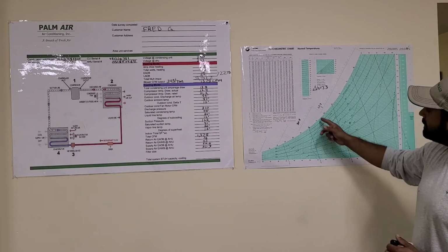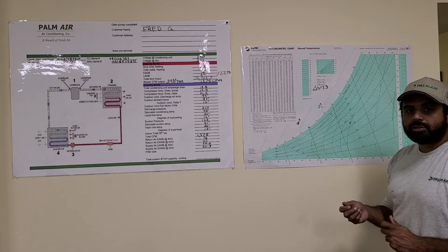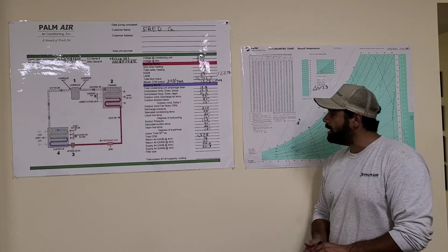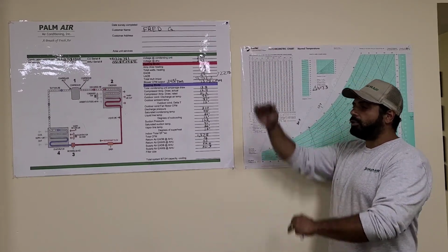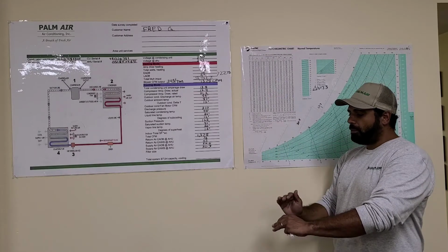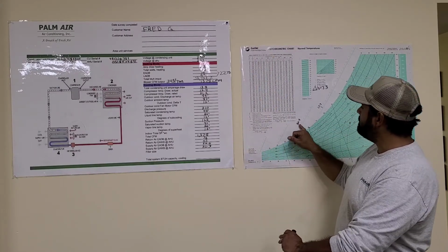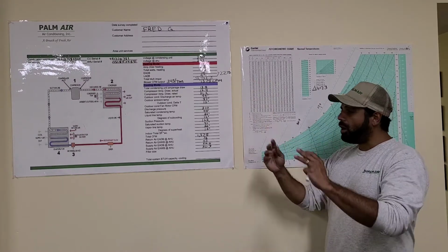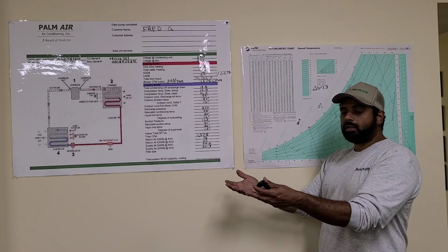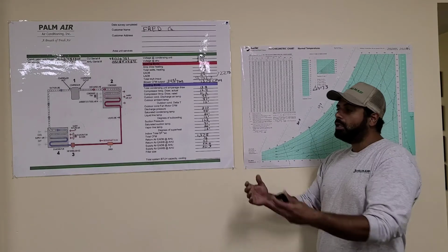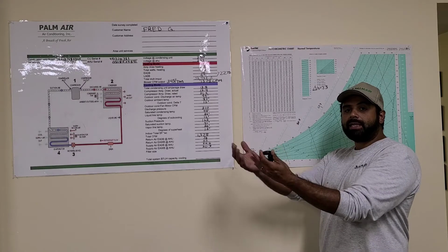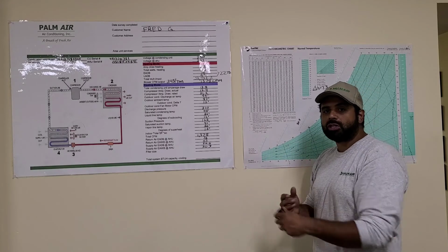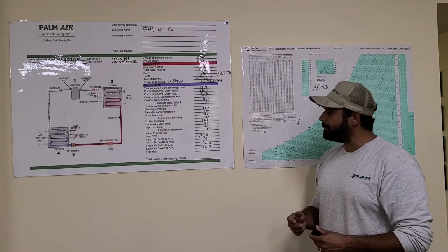Just to put that into perspective, guys, we're taking temperatures at the return air, so just at the bottom of the air conditioner if we're talking about a vertical air conditioner, and then just at the top. So your air handler might be 60 inches high. So from this point to this point, that is the amount of heat that we have actually removed out of that air in just that small time frame. Again, all we're doing is bringing air across a cold coil, and that's forcing both sensible and latent heat to be removed from the air, which we are dumping back into the space. That process happens over and over as we exchange all the air in the home over and over.